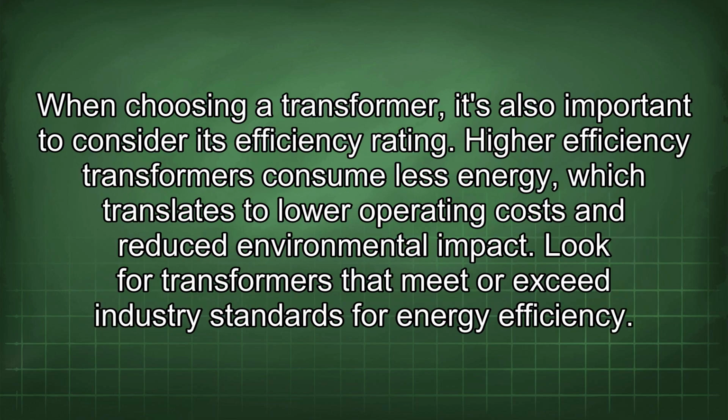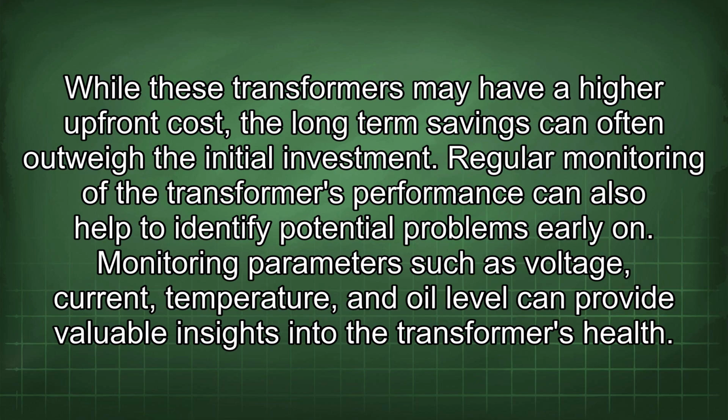Taking a proactive approach to future needs can ensure that the electrical system remains adequate and efficient for years to come. When choosing a transformer, it's also important to consider its efficiency rating. Higher efficiency transformers consume less energy, which translates to lower operating costs and reduced environmental impact. Look for transformers that meet or exceed industry standards for energy efficiency. While these transformers may have a higher upfront cost, the long-term savings can often outweigh the initial investment.